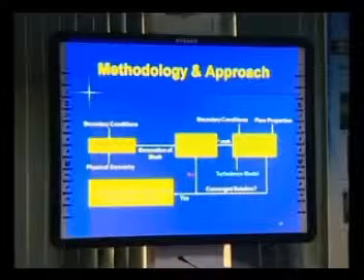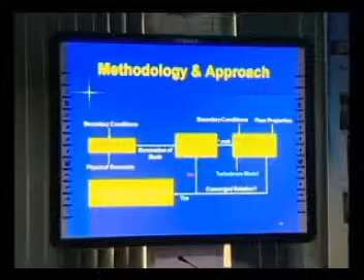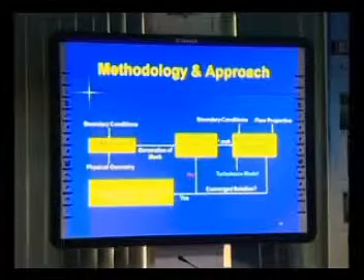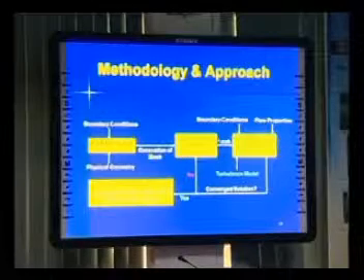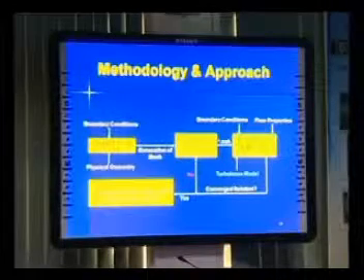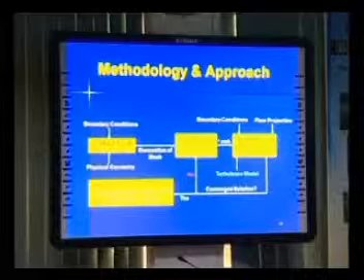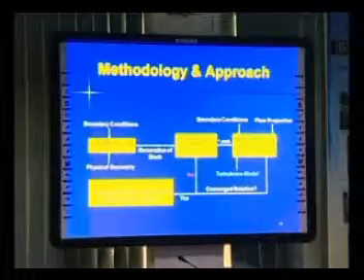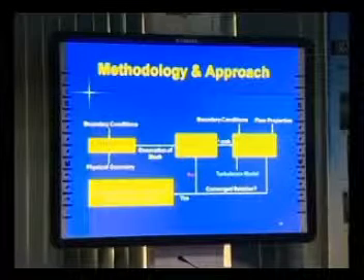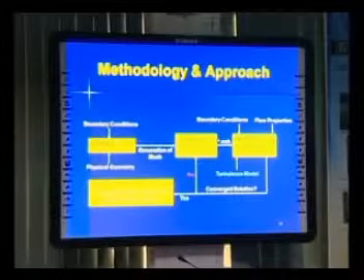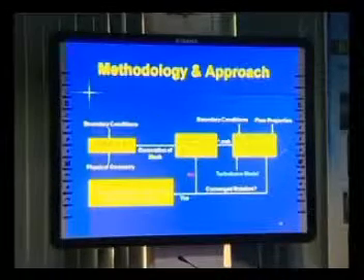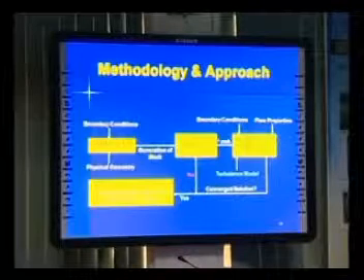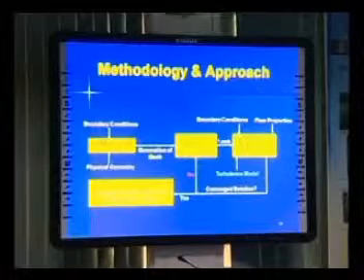The mesh points will assist you to solve all transport equations throughout the domain. And then once the computational domain has been created, you can export it as a mesh file to your main software, which is the CFD tool, Computational Fluid Dynamics tool. This is a commercial software which I have used, known as ANSYS Fluent 6.3.